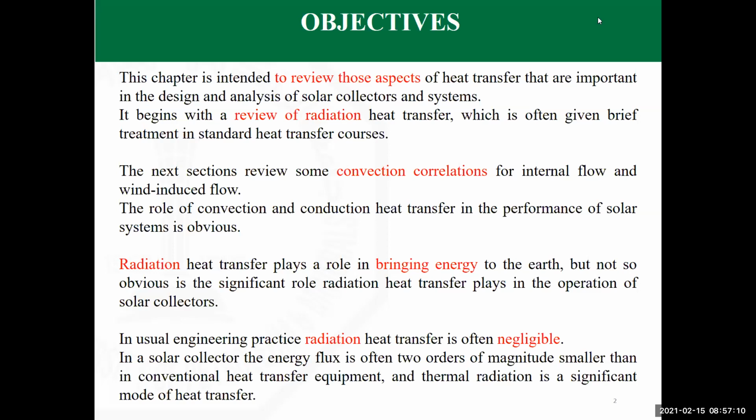Why? Because again, a high heat transfer coefficient is something we need. Even the design of flow around or across tubes can be done so that you generate as much turbulent flow as possible. If you covered flow across tube banks in the heat transfer course, you can see that the critical Reynolds number is quite a bit less than 2000.